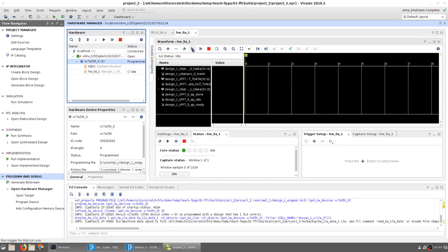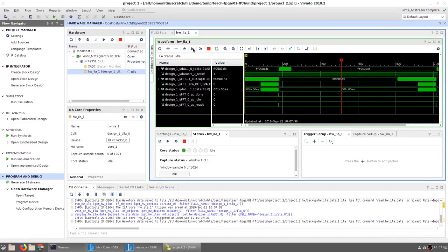And now, since the FPGA has been set up, the design has been set up in such a way that the FFT is scheduled to start, that is its start signal is permanently set to 1, it would automatically have started as soon as the system switched on and the clocks stabilized. So this is an example where you can actually see that the AP done signal occurs twice. In other words, at this point over here at cycle number 179 and at this point over here in cycle 1012. The difference is somewhere around the 800 mark that was actually reported by Vivado HLS and seems to match exactly with what we expected.